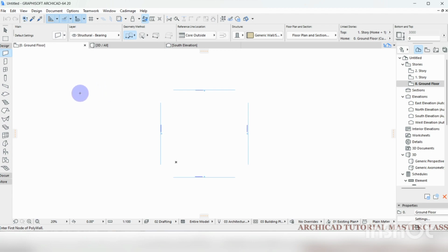Let's say you design a window and you want to pick that window's quality or property and match it to other windows so that they can appear like this. You can use this pickup parameter. So you pick up a particular parameter and match it to other ones. They will now assume the quality or the shape, everything about that. So that is what these tools in this standard bar are all about. By default, it's located here, and they are dockable.